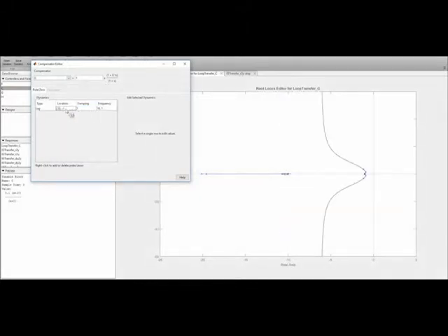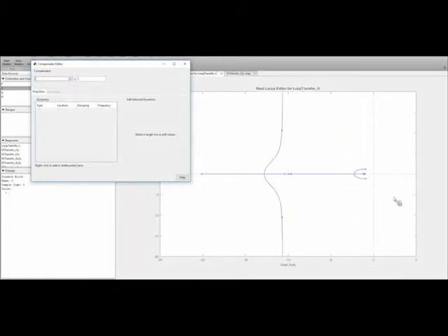Okay. So let me delete that for a second so you can watch this in real time. Going back to where we were, this was the root locus plot for just proportional control with a gain of 1. We said that transiently that's sufficient, so we're good there. What we're trying to do is add a lag controller so we're not sufficiently distorting this root locus plot here.